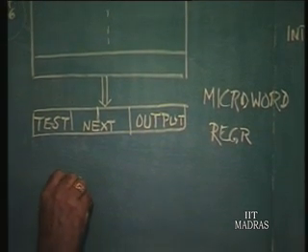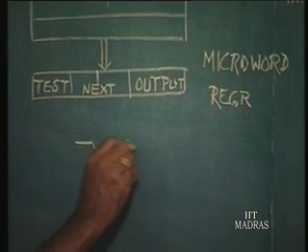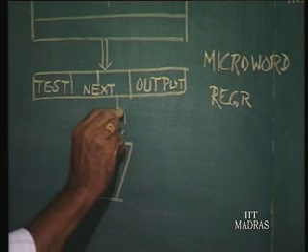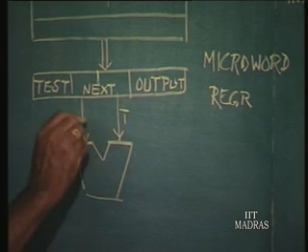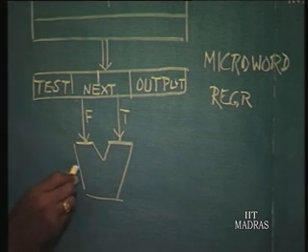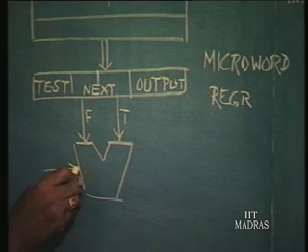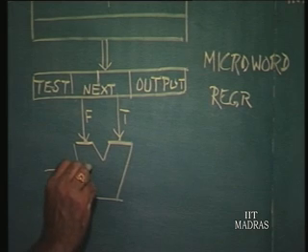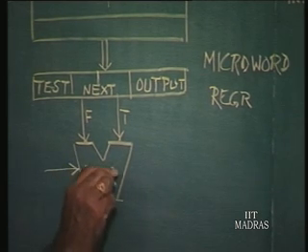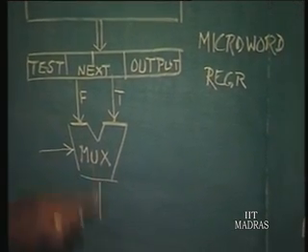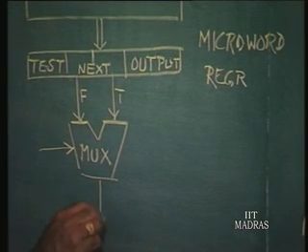So we would have a selector here, to either pass on the true next state or the false next state, which is again a 6-bit code. And there will be a control signal. What is a control signal? Essentially this is a multiplexer, which you have seen earlier. It passes on either this input or that input onto the output.